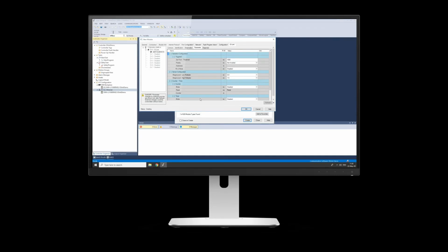You haven't got to do a message instruction to the sensor, which you can do, which I'll show later on in a different demo. I'll show you how we turn the LED on to locate where it is. So the locator LED there is disabled. You can use this when you're online, and it will actually turn the locator LED on. But I'll show you how to do it from software, like we did in the demo before, where you could toggle it from a button. So we can do what's called a message instruction to the sensor, which will then toggle this bit on and off from the sensor.